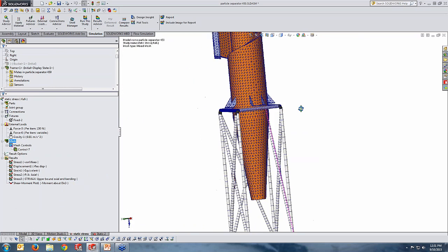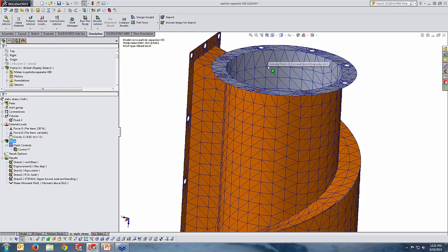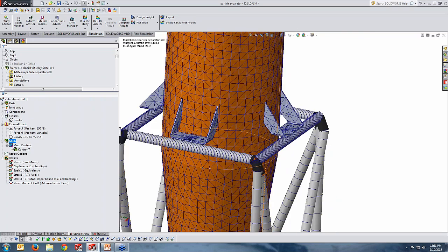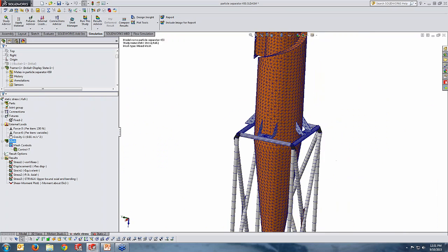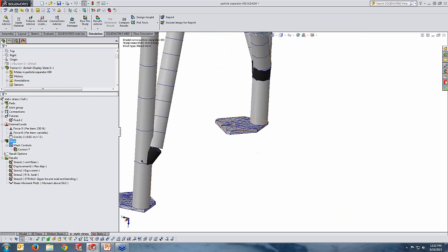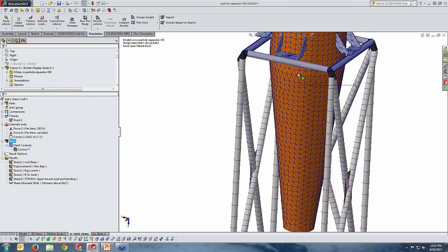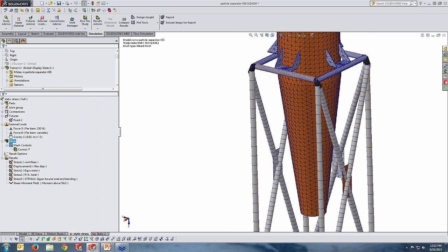So this is my mesh, as you can see. Shell elements with no thickness on it, solid elements with a thickness on it, and we have the structural members with a beam element connecting to, again, solids. What we said in this approach is more than important. Everywhere we have 2 different types of elements, like beam and solid, or beam and shell, we need to have a local contact set at those places.